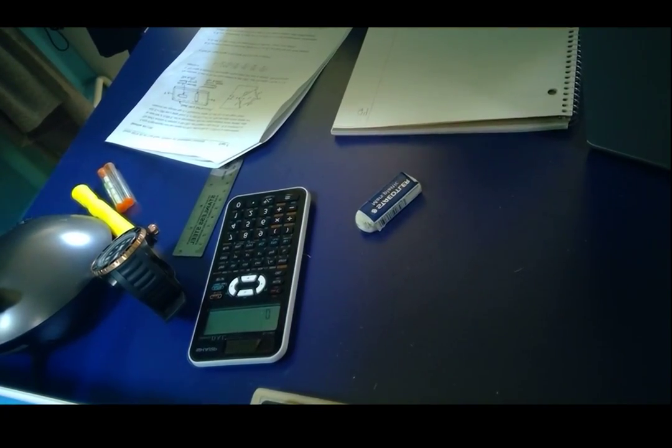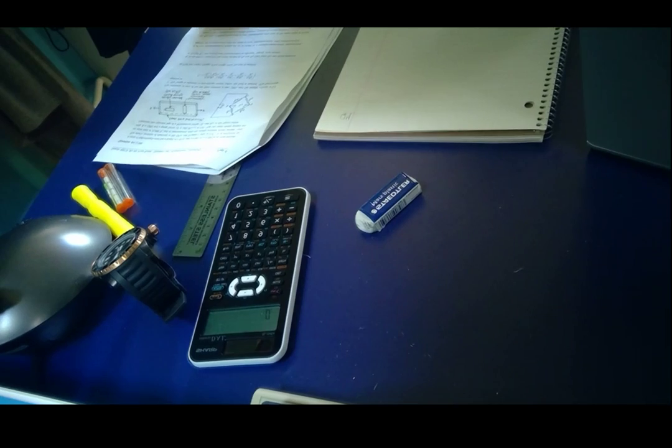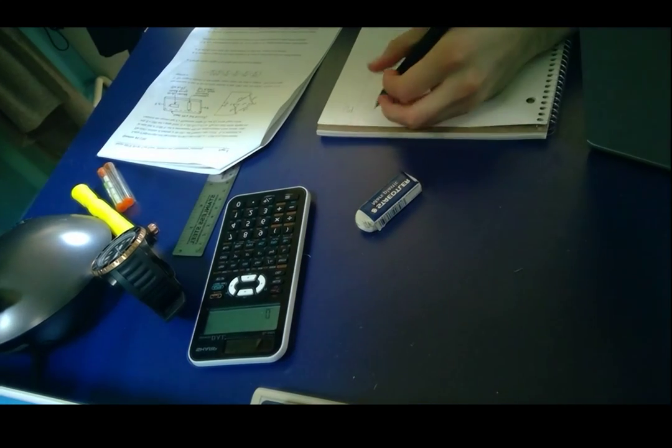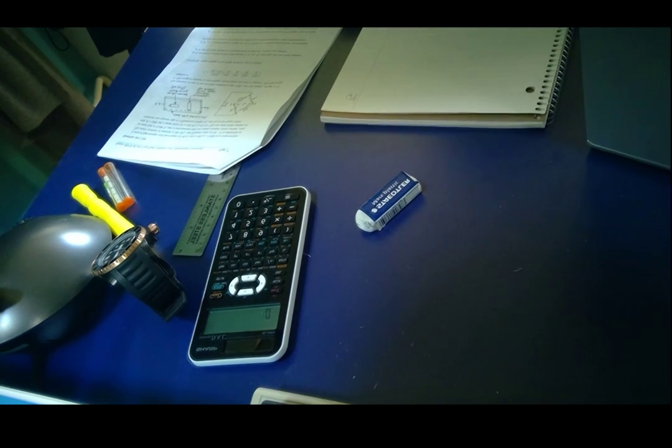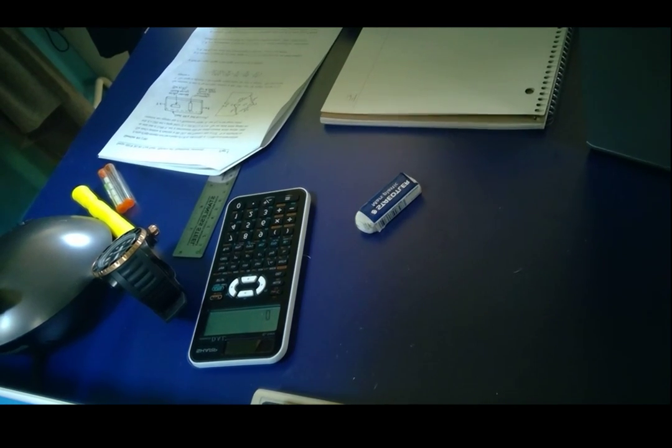The resistance of each of the 2 fixed resistors is also 120 ohm, and the power supply voltage is 2.5 volt. The bridge is adjusted to 0 voltage output before the load is applied. The full bridge equation is this. He gives us the full bridge equation. Find the output voltage of the bridge when the load is applied.